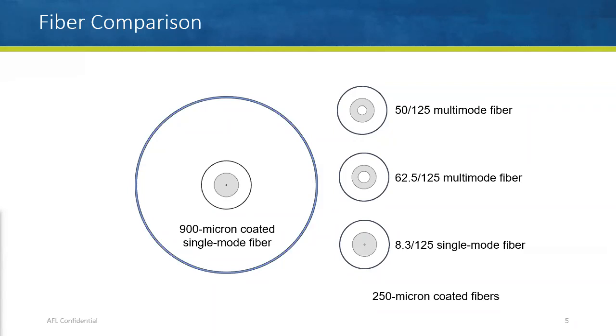This is an additional illustration where we have a little bit more about the different types in different sections. Multimode fiber, which is one of the more common ones, has a larger core down the center, and it allows us to pass more diffuse light, and we use different optics to run that. It's typically LED driven, compared to single mode, which is much smaller. You see how small that dot is in the center; that requires a laser to hit it, so the light goes right down the core, down the center of it.